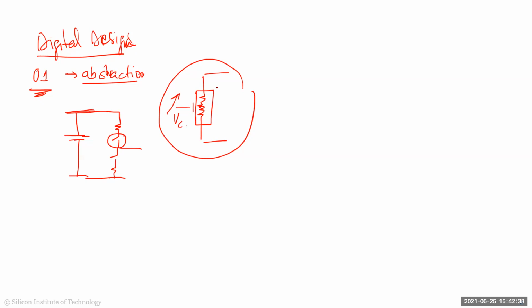So what we are going to first do is derive the expressions for what's called threshold voltage. The threshold voltage is basically, if I take this example, that voltage above which this resistor, you can say, turns on. So it's like you have a very high value resistance, like mega ohms or giga ohms, after which value of this control voltage it turns out to be a lower ohm resistance, 1k, 100 ohms, 500 ohms, whatever it is, right? And that's the key in controlling this device with the threshold voltage.